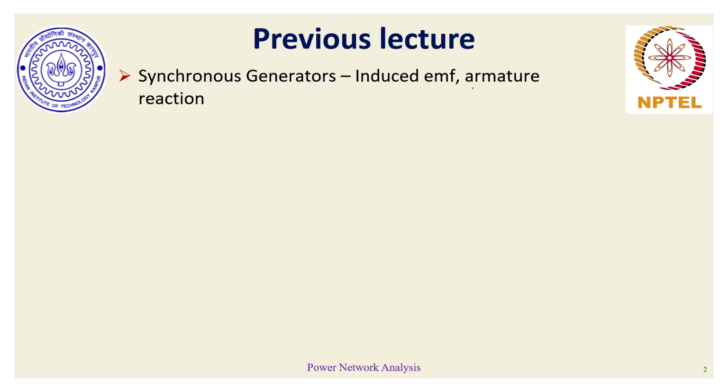is not feeding any electrical load, there is no notion of the stator winding reacting to this rotor flux which is present through the air gap. So when the generator is feeding some electrical load, the stator windings also carry three-phase balanced currents, which leads to creation of stator MMF, which opposes the rotor MMF, and as a result the air gap net MMF, magnetomotive force, is a combination of rotor MMF and the stator MMF.